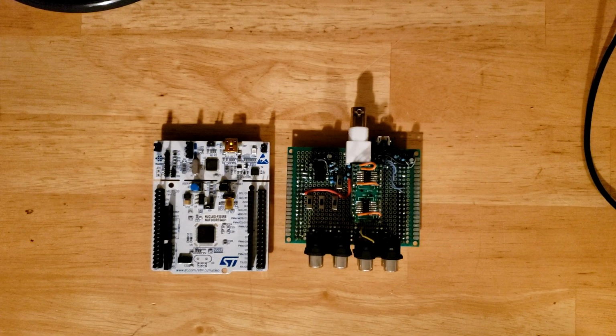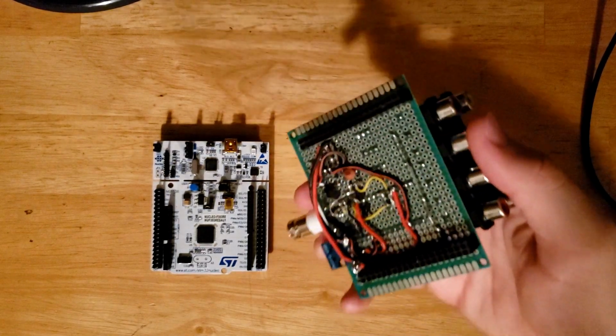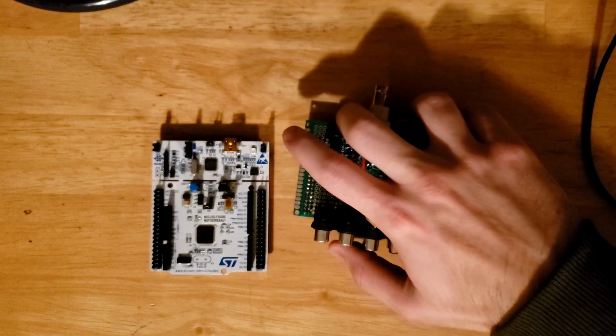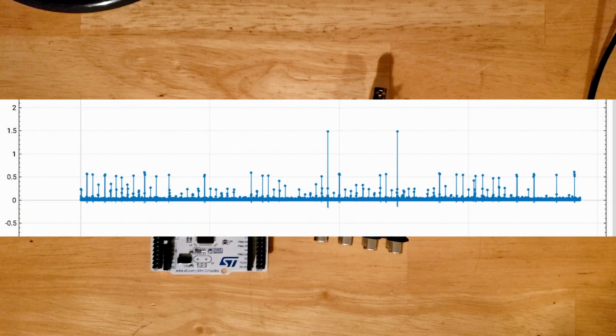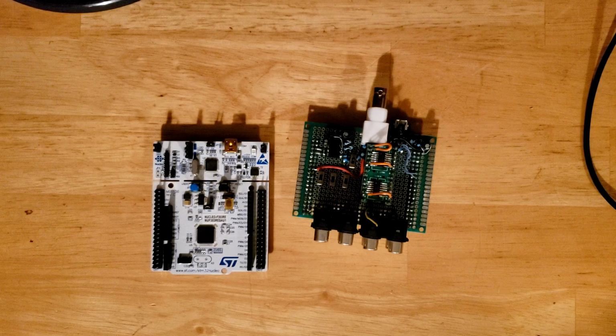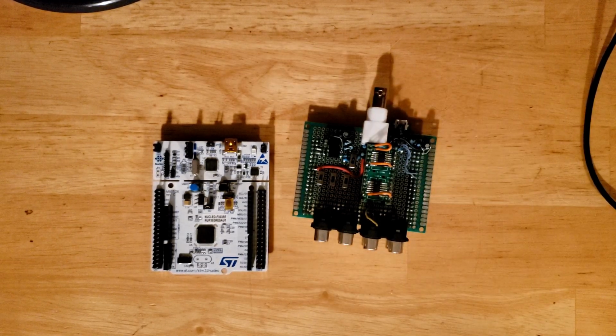Before I actually purchased the PCB, I wanted to try out the hardware. I soldered up this prototype board with the equivalent we saw in the schematics and started doing some testing. The first thing I noticed was that the input of the STM32 is extremely noisy. I assumed it to be the unterminated op amps and decided to go through and terminate each of the op amps with these jumpers, which didn't solve the problem.